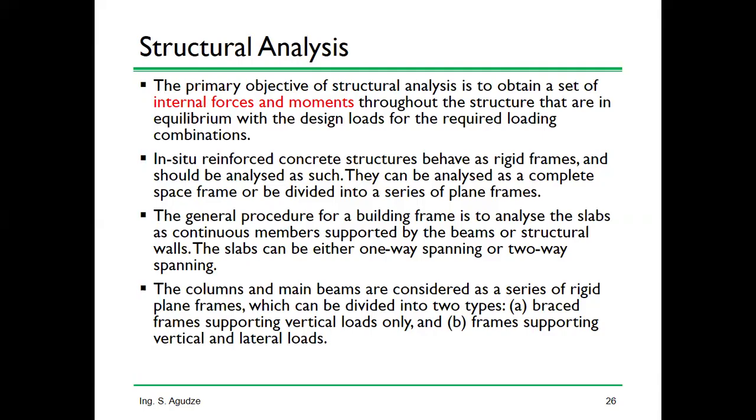They can be analyzed as a complete space frame or be divided into a series of plane frames. So the general procedure for a building frame is to analyze the slabs as continuous members supported by the beams or structural walls. So the slabs can be either one-way or two-way spanning slabs.